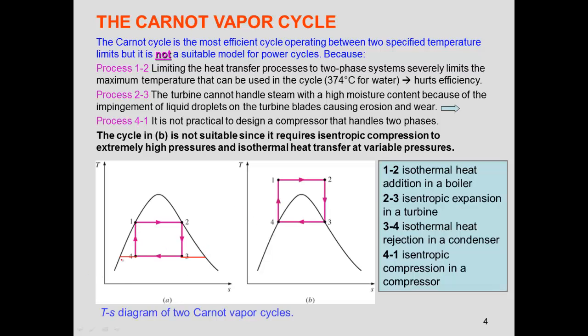This will give us some problems, because now we need to accommodate this. Remember that the isobaric process drawn like this is not to scale. So now we have to pump water to the pressure of the boiler. Then we have subcooled water here. We need to add heat, evaporate, and along the same pressure we are going to have superheated vapor. So let's say that it's this way. Remember, it's not to scale. And then we're going to have the expansion.